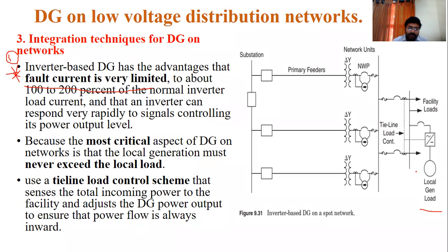There is some precaution whenever you are adding this DC directly to this network. The DC load, or the DC capacity, must never exceed the spot network load.